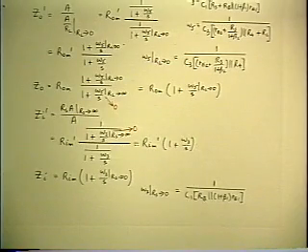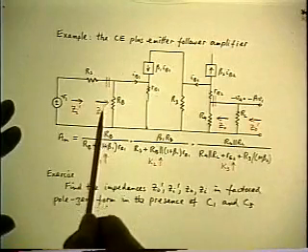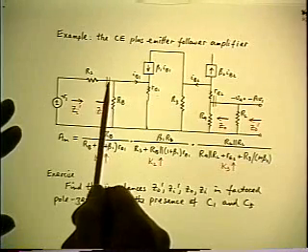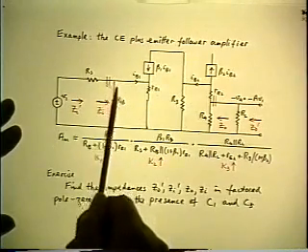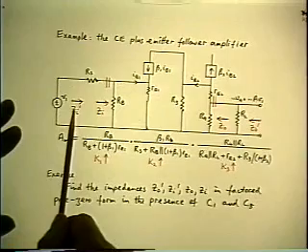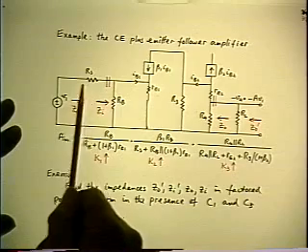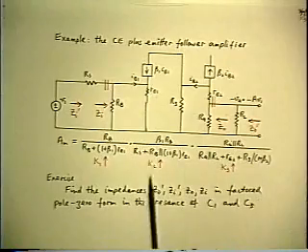And that's consistent with looking at the original diagram also, because the inside input impedance is the mid-band value when the cap is a short, and at lower frequencies the cap starts to open up, and so the input impedance will rise. And the same thing will happen for the outside input impedance. The only difference is the mid-band value is larger. But when the cap opens up at low frequencies, again the outside input impedance will take off and start to rise. So that completes the example of applying the input and output impedance theorem to this particular example.